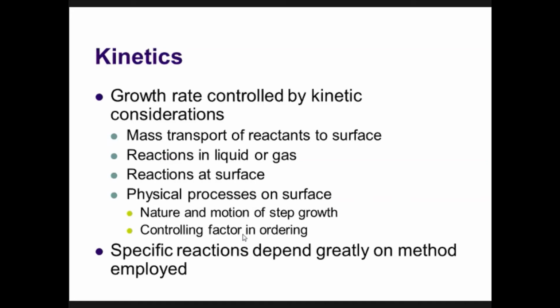Okay, mass transport of reactants to the surface, reactions in liquid or gas, reactions at the surface, then the physical processes on the surface, that is, the nature and motion of step growth, a controlling factor in ordering. Later, when you think in terms of preparing quantum dots, which normally occurs by a self-ordering or self-assembling process, there also we need to control these growth parameters. The specific reactions depend greatly on the method applied, whether it is MOVPE, hydride VPE or chloride VPE. So the reactions depend upon the type of growth technique we are trying to use.